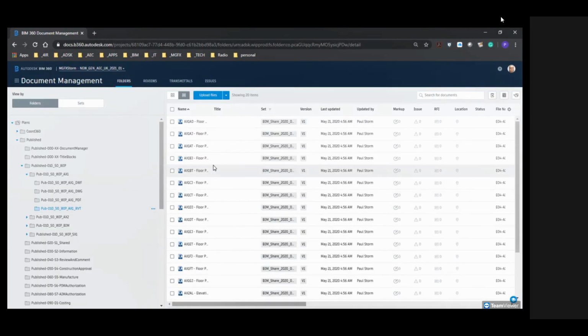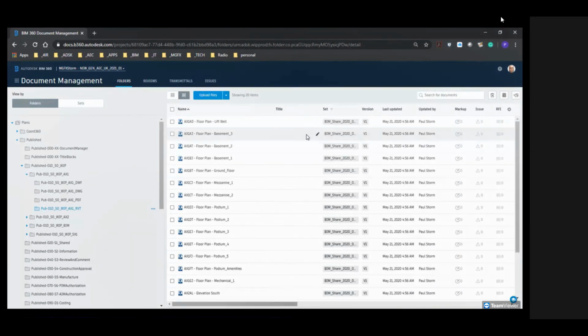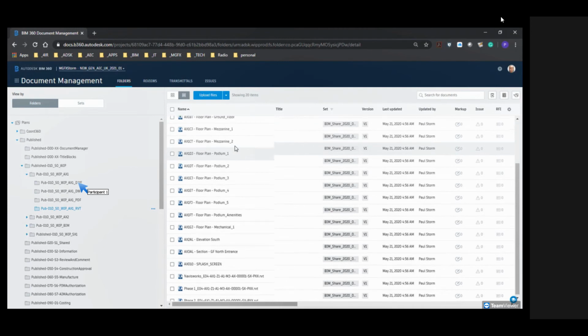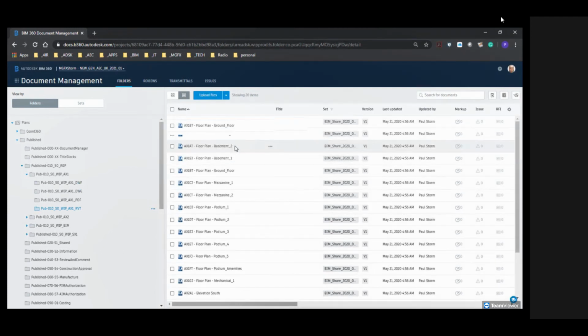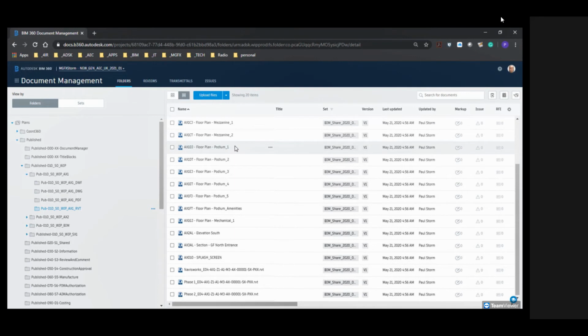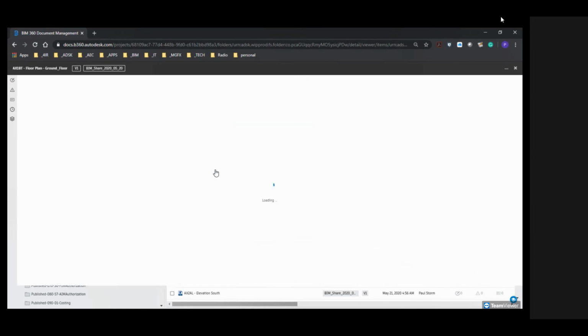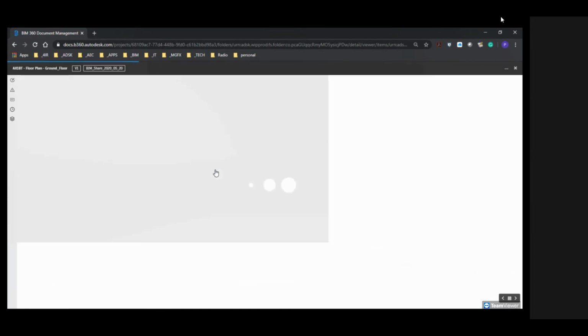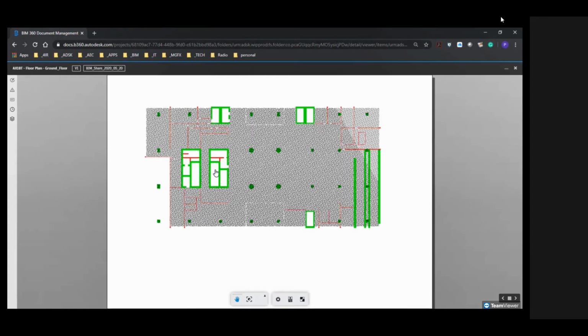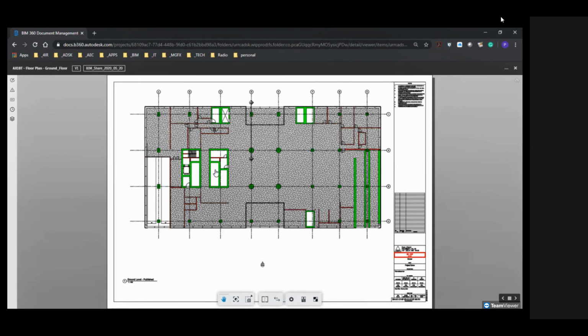Okay, there you can see all the drawings have been extracted, all the sheets have been extracted, and the metadata has not been extracted. So that's the disadvantage of using the Revit way, in that you're still going to have to fill in the metadata separately. For this reason, I like using PDF files. It's my preferred way of working with published files, simply because one can gain access to all the extracted metadata immediately.